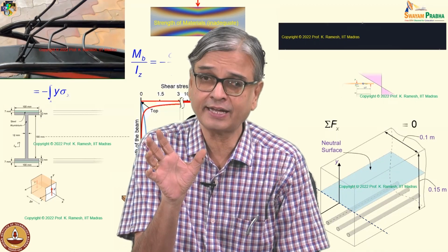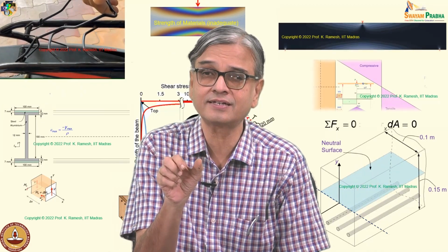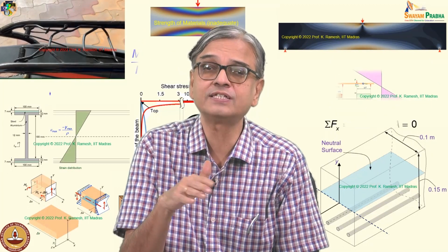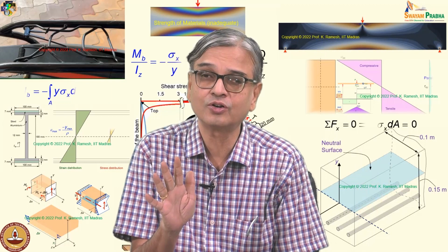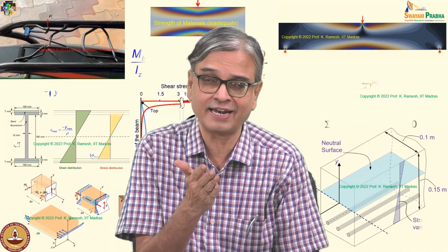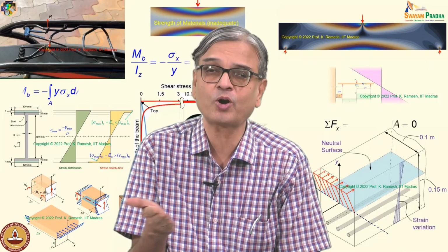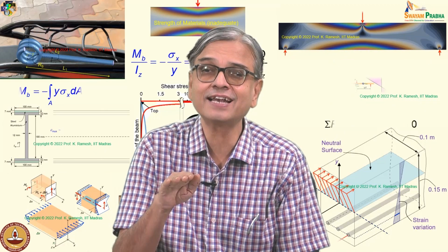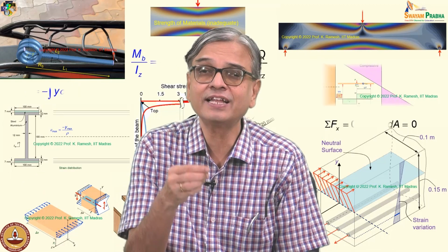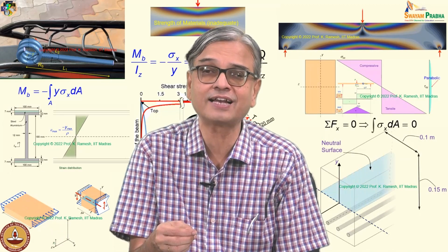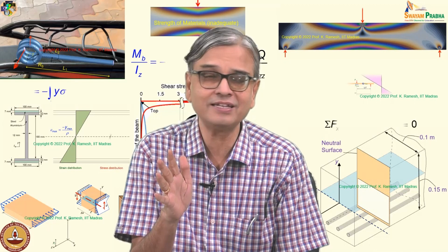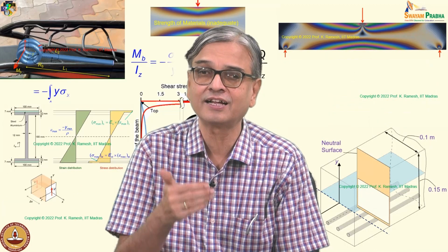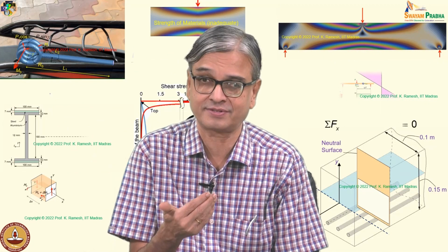You have to be firmly connected. You cannot simply insert it and then say make a beam out of it, or even if you apply the glue which is very weak, it is also not going to work, because we have already seen in the glass plate problem where you want to support the books. If you put an extra glass plate without any connection between the earlier glass plate, its strength was very small, because we have done the experiment when we want to understand how shear stresses are developed in the beams.